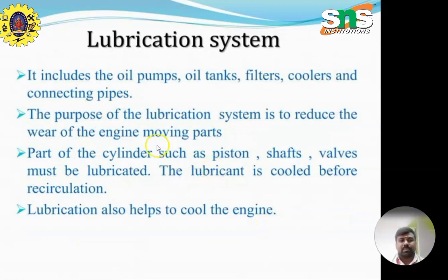The lubrication system includes the oil pumps, oil tanks, filters, coolers and the connecting pipes. The purpose of the lubrication system is to reduce the wear of the engine moving parts. Parts of the cylinder such as pistons, shaft and valves must be lubricated. The lubricant is cooled before recirculation. Lubrication also helps to cool the engine.